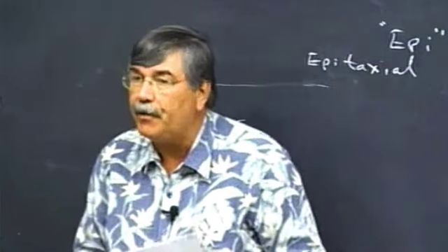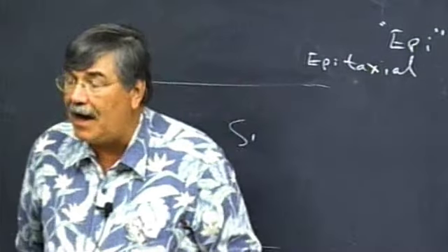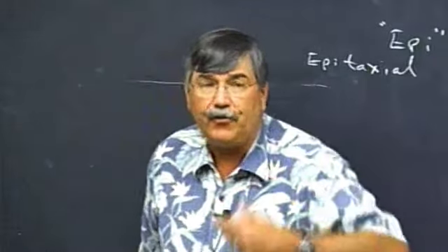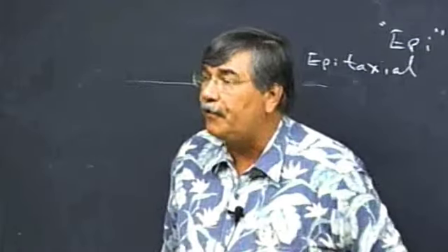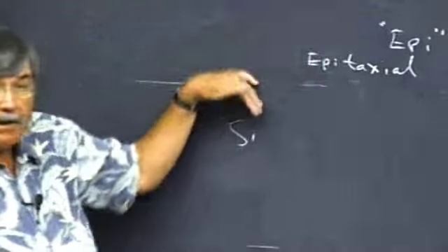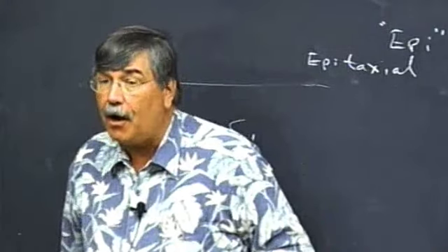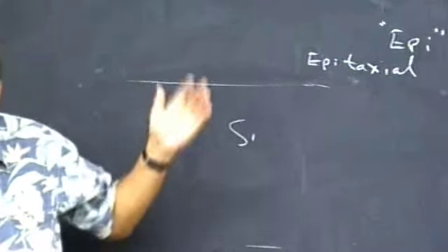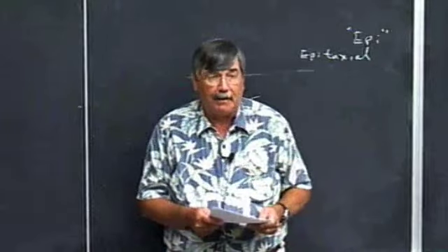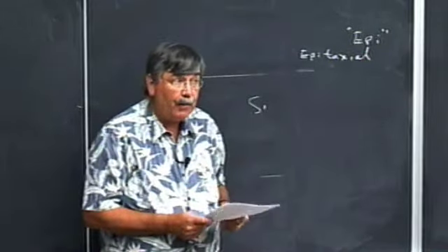Ways to put impurities into the material. The number one these days especially is ion implantation. As I mentioned, you just ionize whatever it is you're trying to put in there, put an electric field on there and shoot the impurities directly at the wafer from above. How fast you shoot them, how much energy you give them, controls how deep they're likely to go, and how many of them you put in, the actual current integrated dose, you can count them. You can just integrate the current and figure out how much stuff you've put in per unit area of the wafer. So it's a very well controlled process.